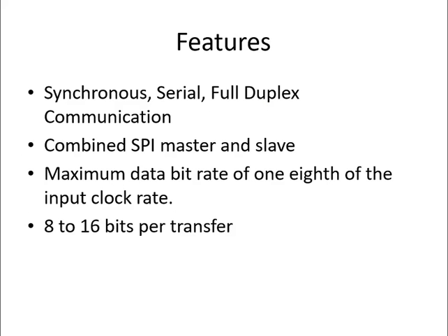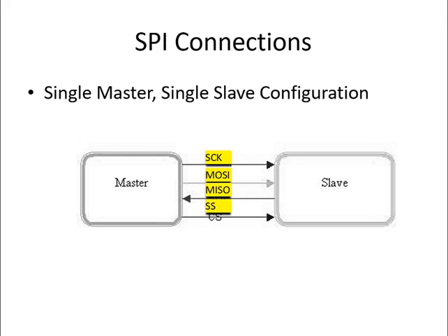Now, what are the features available in case of LPC2148? It is a synchronous serial full duplex communication. It combines SPI master and slave, so you can have both master and slave configuration available. Maximum data bit rate is 1/8 of the input clock rate and it transfers 8 to 16 bits per transfer. So at a time it can transfer 8 bits or maximum 16 bits.